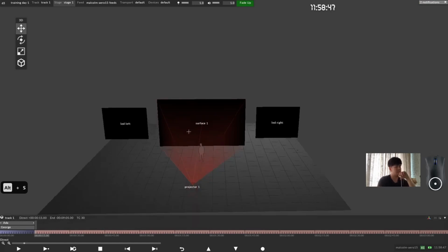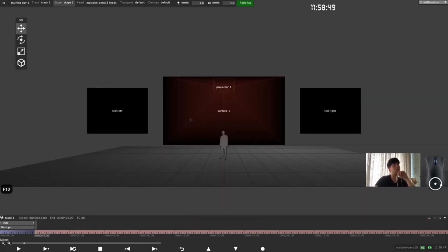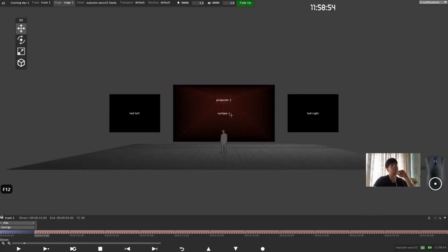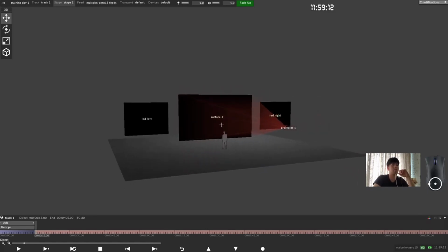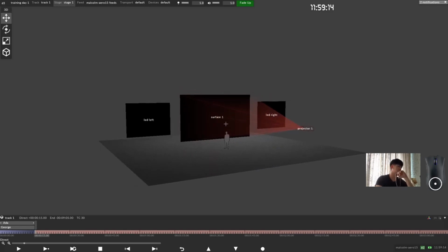Next, we're going to fix camera shortcuts, which will be good for reference. You can instantly jump into that view, for cinema people, photographers, videographers or content guys who want to look at a specific angle. Just move to the left. Holding Alt+F2, you can store your camera bookmark.